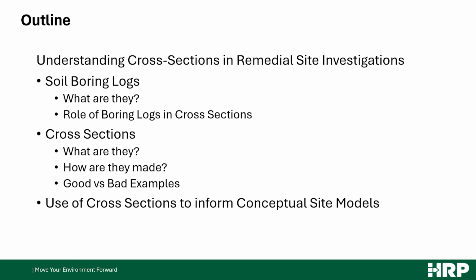So as an outline for this presentation, the whole point is to understand cross-sections, remedial site investigations, their use, but also what information we need to collect that will allow us to make a meaningful cross-section that will be useful for the investigation. So a good place to start is the collection of soil borings and logging the soils, both with observations and a PID.